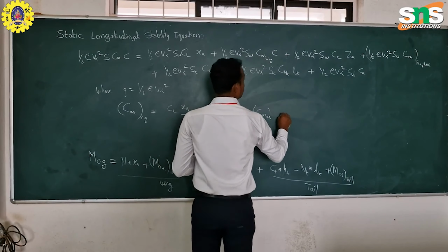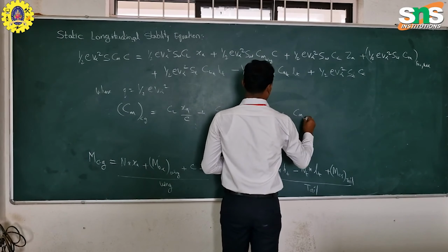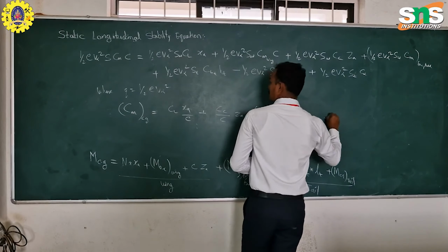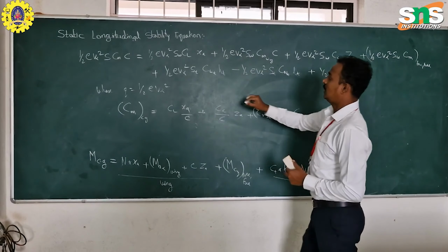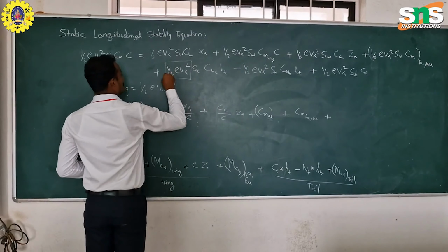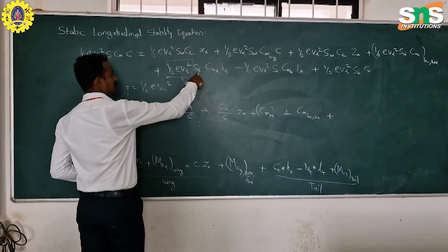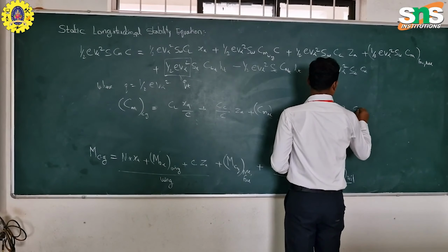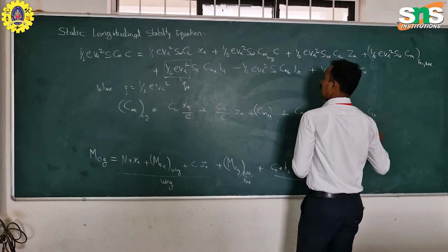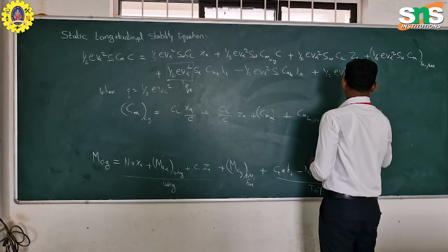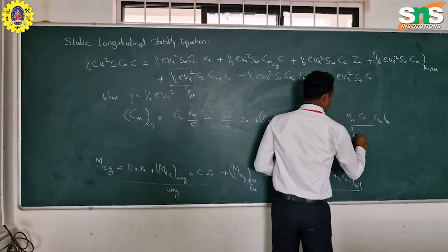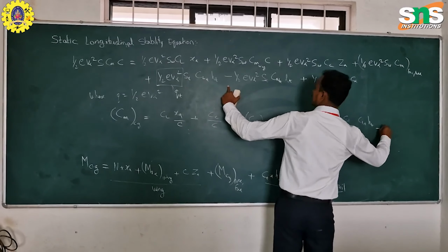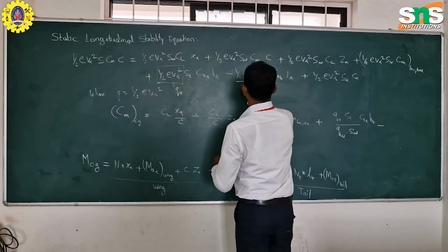This is for the wing term, plus CM fuselage plus nacelle, plus for tail, that is this entire dynamic pressure is for Q tail. So this is ST, right? So we will get QT by Q, ST by SW, CLT, and again minus for this, again this entire term is QT.